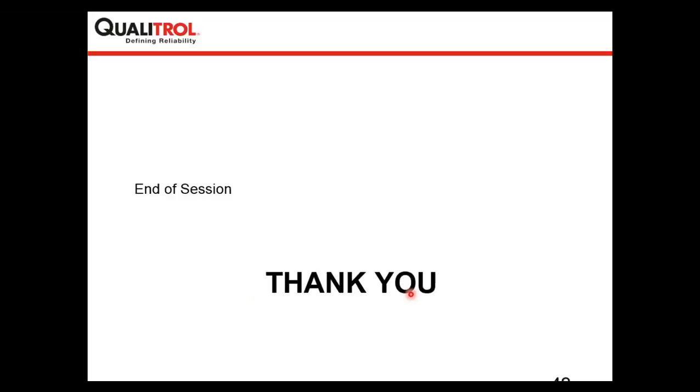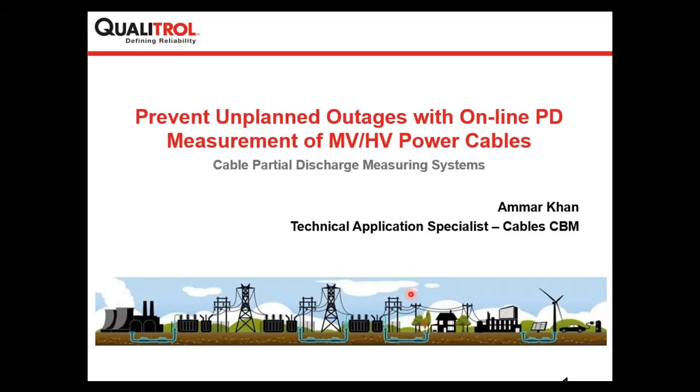It's okay, Amar. We do have a question regarding one of the slides at the beginning of the presentation. Is it true that water trees do not give advanced warning with PD? Yes, this is a very good question. Water trees are formed because of the impregnation of water in the cable insulation in the presence of field. When these trees are filled with water, they will not give any partial discharge in power cables.